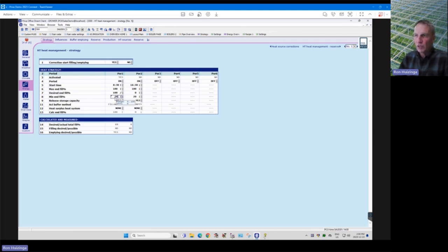So your CO2 starts, and you ramp up from 20% to 100%. But sometimes you get a warm night, so it doesn't use up all the heat, and you don't actually get down to 20%. You only get down to 40%. So if the ramp starts at 20%, that means the first couple hours in the morning, as it ramps from 20 to 40, it's going to say my tank is too full, and it's not going to let the boiler run very hard for CO2.